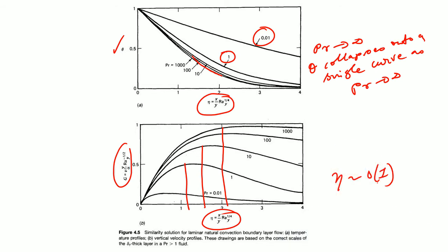This is also very significant because we said that when the Prandtl number is high, the peak of the velocity should happen at delta t, and delta t is basically your eta in this particular case, because eta and delta t are basically the same. So, that is what it is over here: at eta of the order 1, I mean just about 1, when it is around 1, the portions of the velocity profile approach kind of a single graph. So, these also start to stack up. If you draw the next profile, it will be somewhere like that, right.